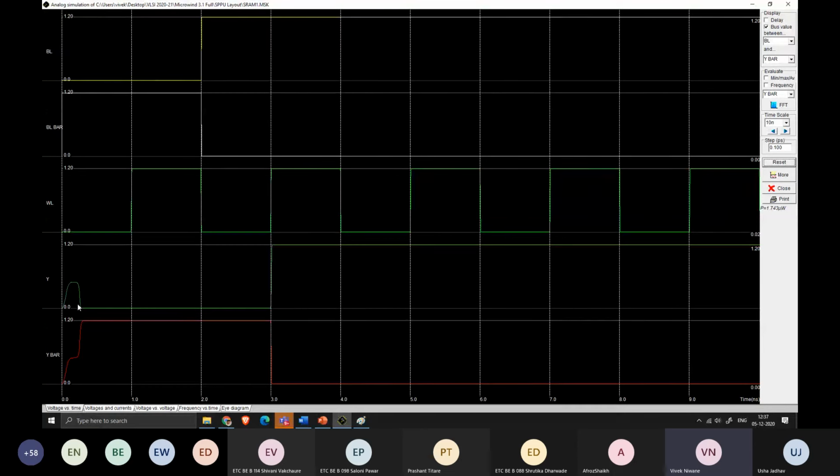Okay, ये starting में जो glitches आ रहे हैं, those are due to the internal capacitances of your devices. बहुत सारे parasitic capacitances होते हैं, diodes होते हैं, transistors होते हैं, everything you do have inside the MOSFET. Okay, due to those, it gets stabilized in the starting few nanoseconds. It takes around 0.3 or 0.2 nanoseconds to stabilize its voltage values. Therefore, we do have spikes over here.